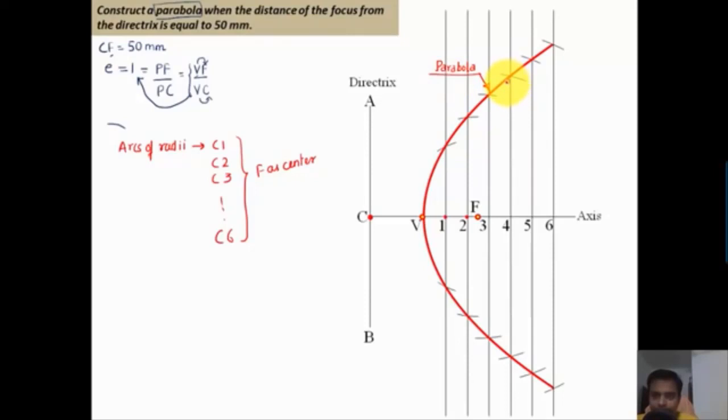Now let's say this is the point where we need to place a tangent and a normal. Let's say the name of that point is P. Okay, so the first thing that we've got to do is to join this P with this F over here. Okay, let us do that, and then we need to make a line perpendicular to this PF line, something of this sort, such that this angle shall work out as how much? 90 degrees. So this can be done very easily. You can do so with the help of your mini drafter or simple protractor.